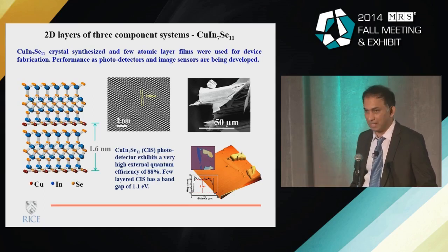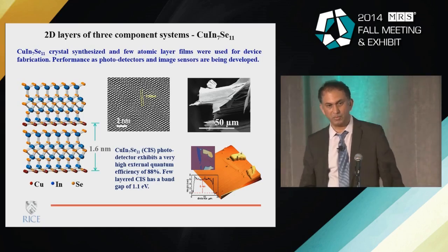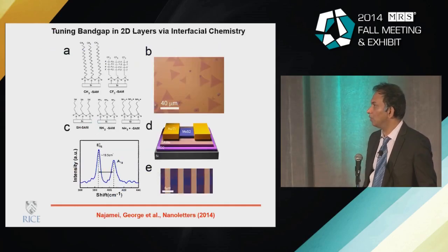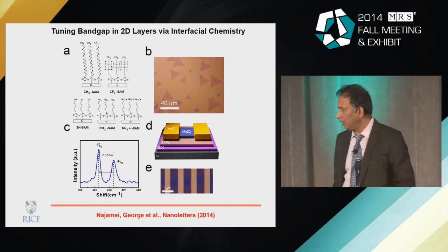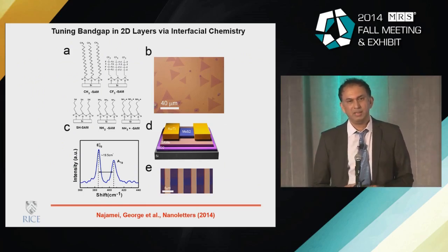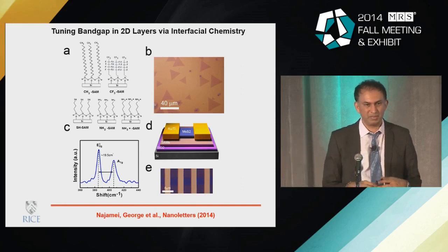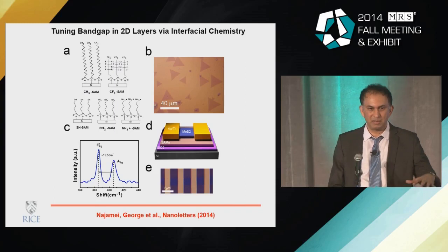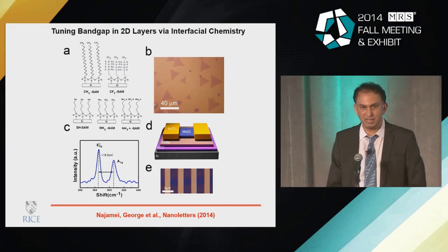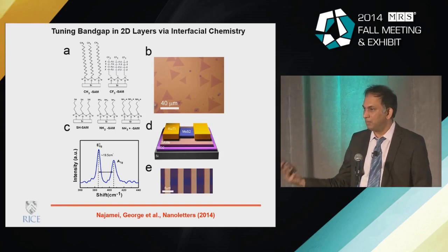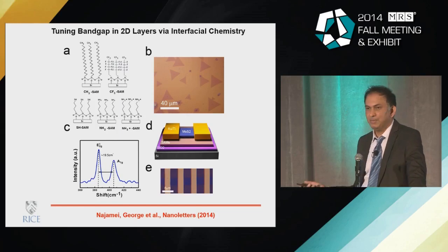And copper indium selenide again is a material that has been used in photovoltaics and so on. So it's interesting to know that you can actually grow them in monolayers. As I said already, the substrates make a big impact on its electronic behavior. You already saw that picture where if you put graphene on silicon oxide, your mobility goes down dramatically. But if it's sitting on some other substrate like boron nitride, it's pretty good. So again, there is a large number of possibilities to create devices on different types of substrates.